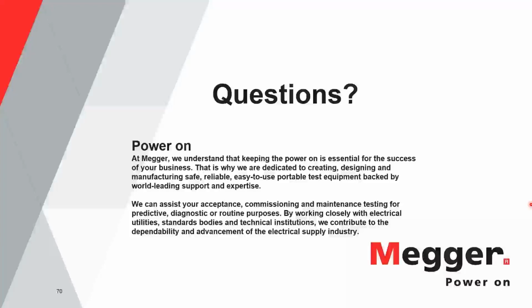Second thing here, if you don't have our instrument, we also have a viewer, just something that you can use to see all of the type of files that are out there that can measure SFRA or can do SFRA tests. And then the third thing, talking about our software, for the analysis we have different tools. So the first tool that we have is the difference. So you can compare two different traces and the software will calculate the difference between them, and you can see if there's a difference in magnitude, difference in frequency, or difference in phase as well.